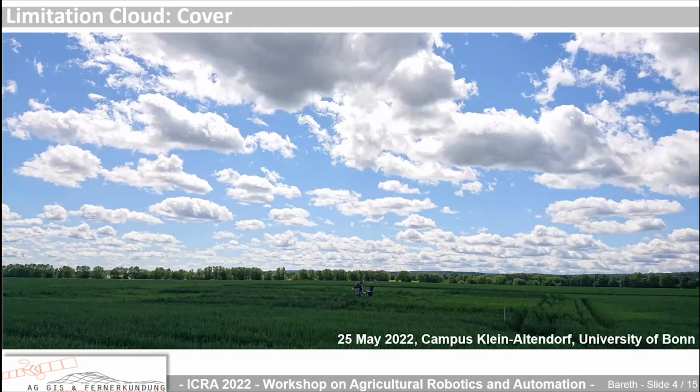If we fly our UAVs, sometimes we fly for 10, 20 minutes. And on those days, it's almost impossible to find a slot where we have constant irradiation. Sometimes the drone is in the sun, but the picture it makes is shadowed, or vice versa.